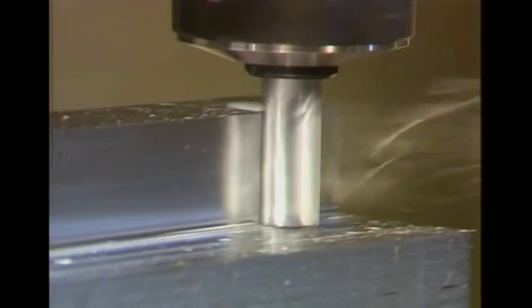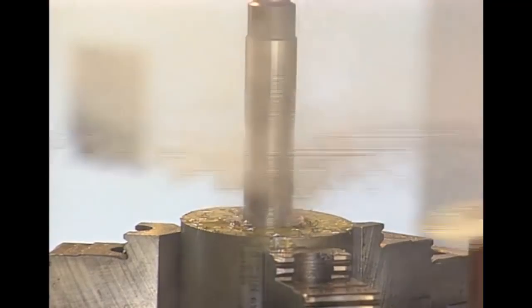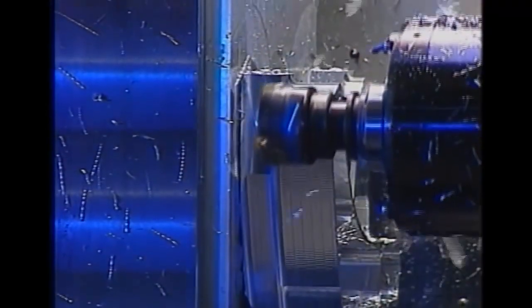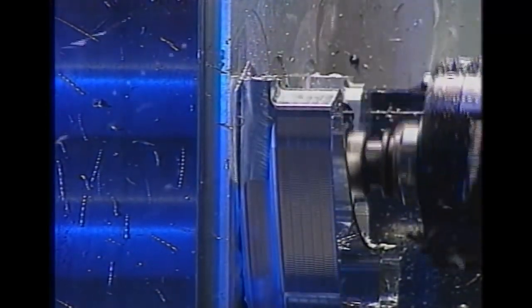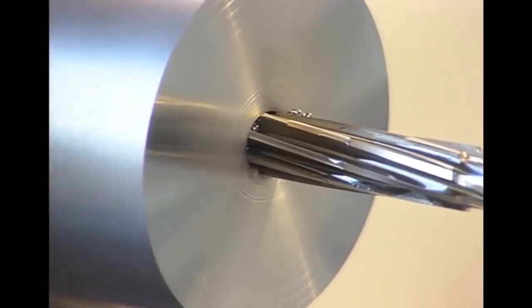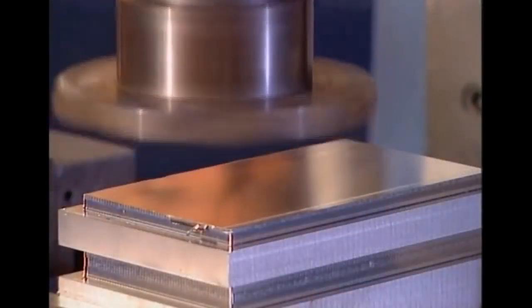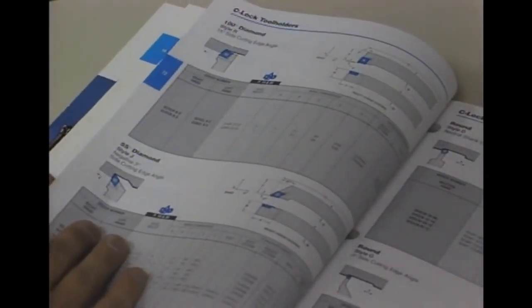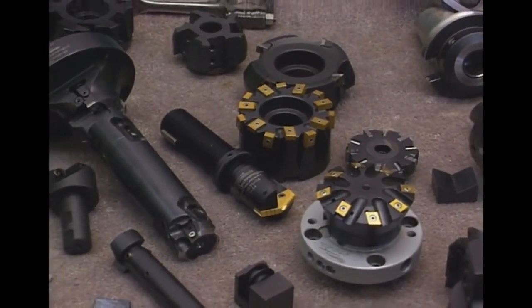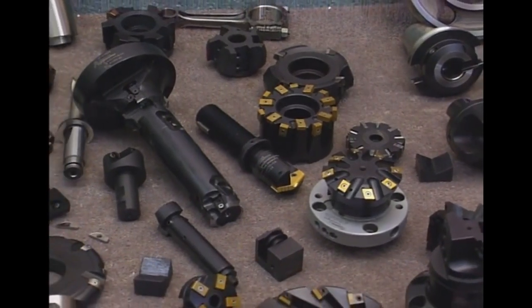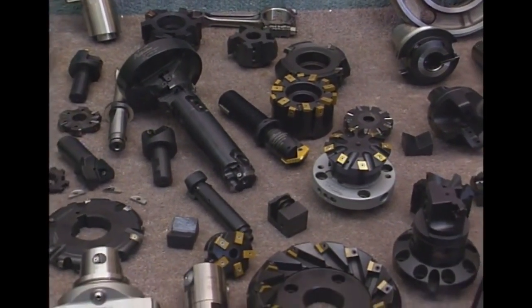Tooling incorporates thousands of different cutting tools and tool holders for discrete parts manufacturing. Principal categories within cutting tools include single-point cutting tools, such as lathe tools, multi-point cutting tools, such as milling cutters, drills, reamers, and taps. Cutting tools are either standard tools, which are purchased as catalog items, or special tools, which are designed and built for a special machining job, often to suit a particular workpiece.